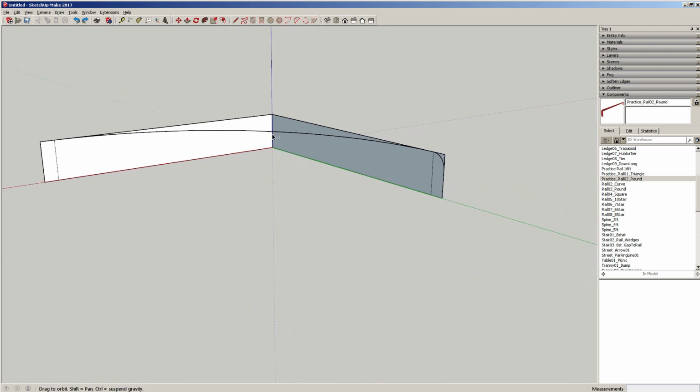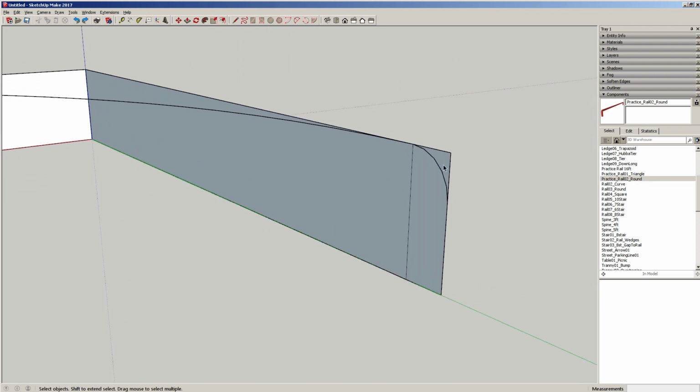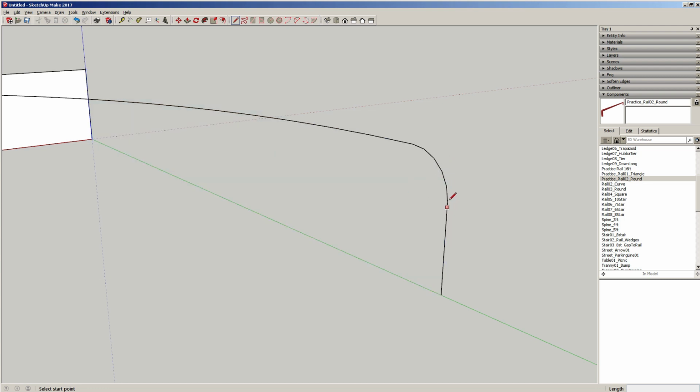Right? Now if we want the same circle, same curve we have here, we could do that copy. But notice it didn't create a face for us. Should have, but it didn't. Another way we could do it is select. I'm holding Shift to select more than one line.